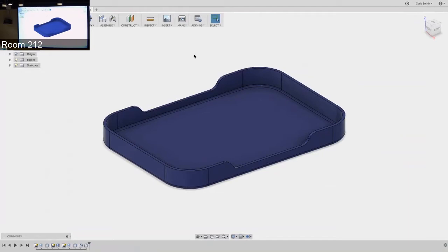How much error? Right. Okay, clearances. Gotcha. In a non-3D printed world, clearances are a big subject, and machinists who work with metal and subtractive processes will talk clearances all day long. For what they call a loose fit, you're usually looking at 9 thousandths of separation, maybe 11-ish, something along those lines. You could convert that to millimeters, it's about 0.2 millimeters.